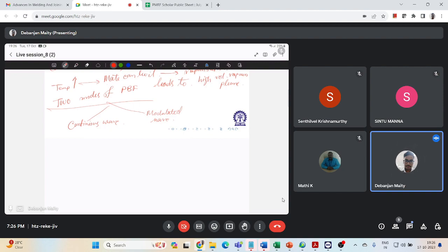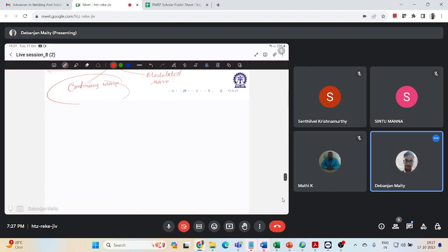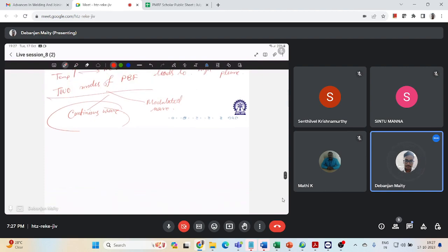And what is scanning speed? Scanning speed is the velocity of the laser spot, correct, which traverses across the bed. Now, for continuous laser melting, it is defined by the distance traveled within a certain time step, while in modulated melting, it is defined by the exposure time.